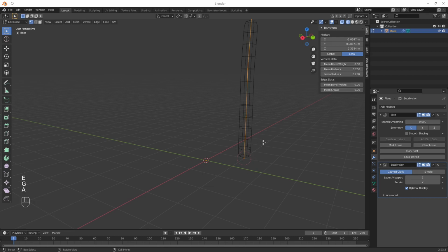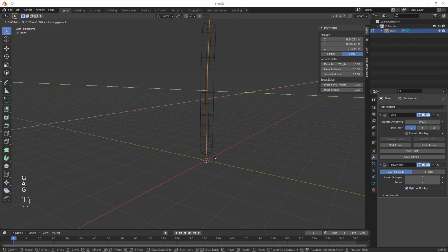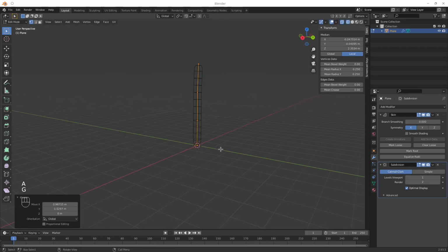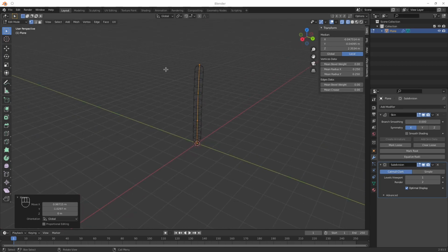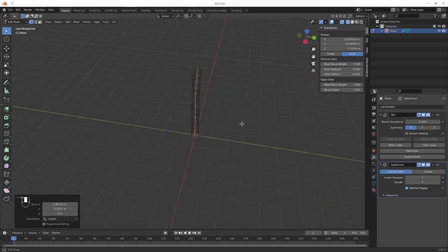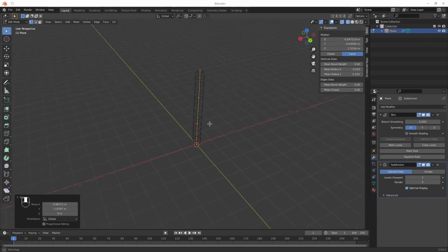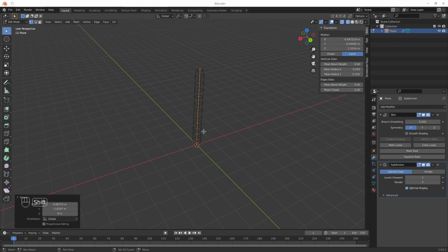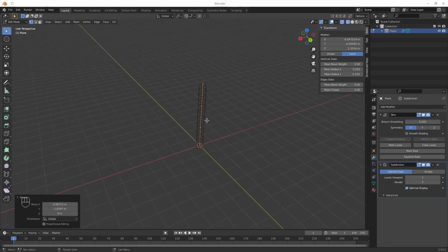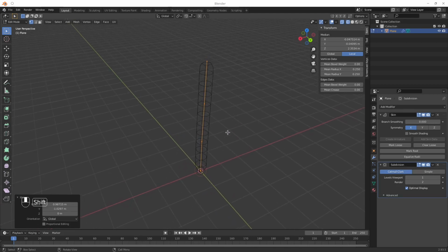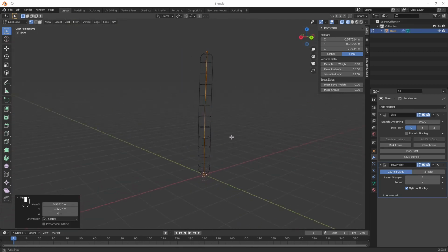Let me select all and move on the plane, something to the center like that. And if you want to pan the entire window, pressing down on the mouse wheel will orbit, but if you press shift when you do that, you will pan around.